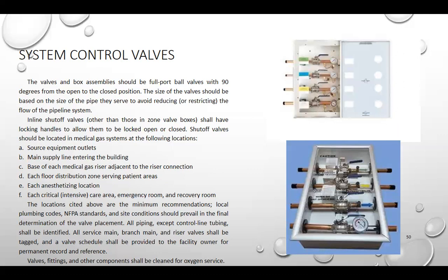D. Each floor distribution zone serving patient area. E. Each anesthetizing location. F. Critical area, intensive care area, emergency room, and many more. So these locations cited above are the minimum recommendations. Local plumbing code and NFPA standard and cited conditions should prevail in the final determination of the valve placement.